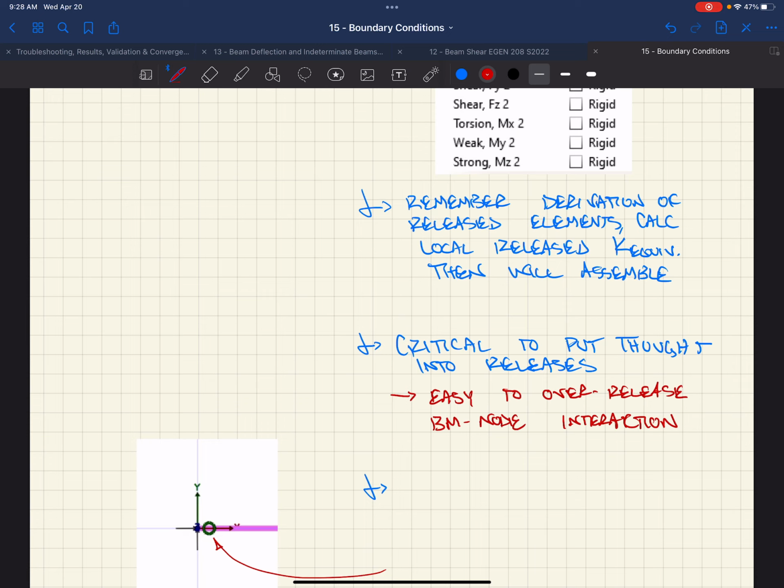So you're talking stability stuff? It's just second order effects. Chapter C or whatever. There's one provision where you can add a bay and then account for all your leaning column effect, the added P-delta that you get from having a bunch of gravity columns displacing a little bit as well. Never done that before. I've always done the moment magnifier method, B1, B2.